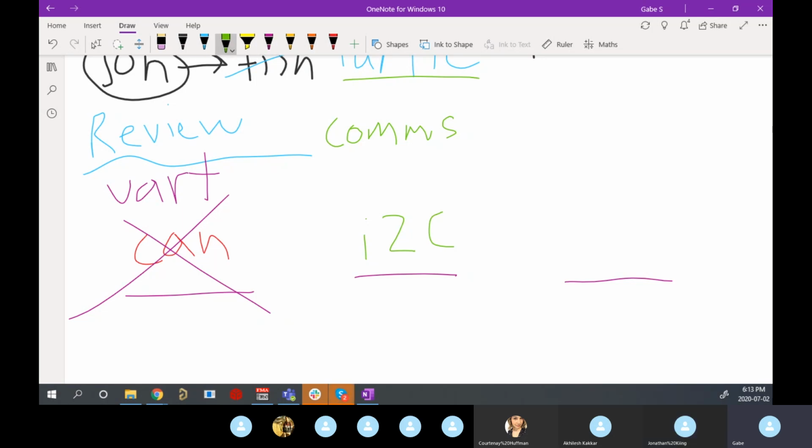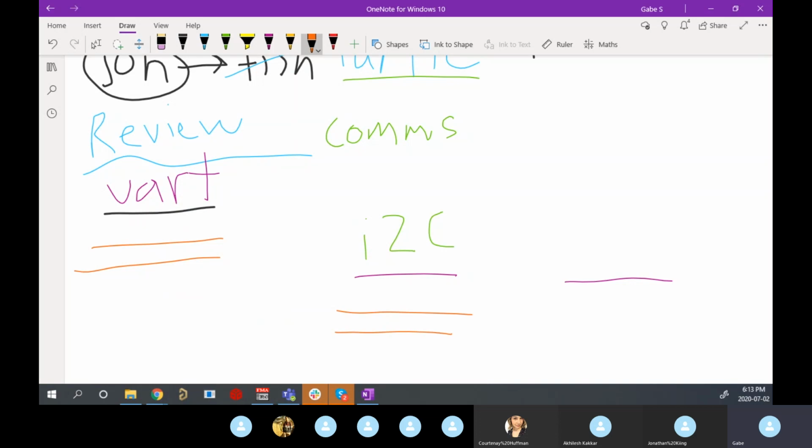Yeah, so we did UART. We kind of talked about it a little bit just because people ask questions, but I'm hoping to have an actual lesson on that, and maybe we'll get some experts to guest speak for us. But we did UART. So the comparisons between these were: UART is a 2-line protocol, so is I squared C. On UART you had RX and TX, right?